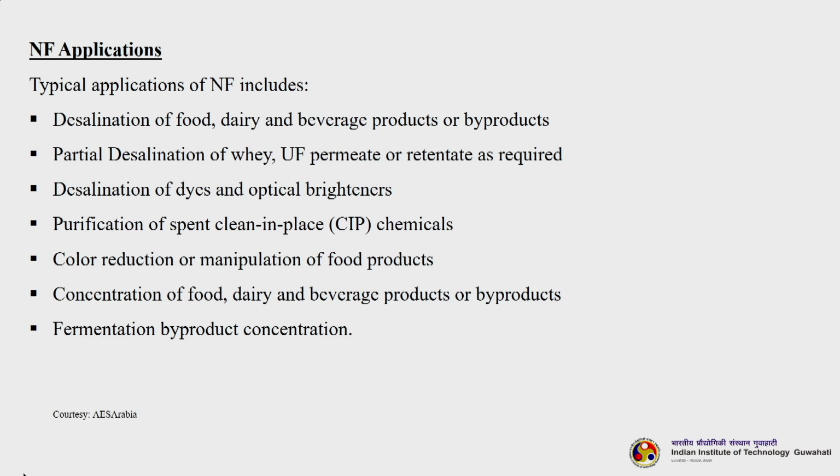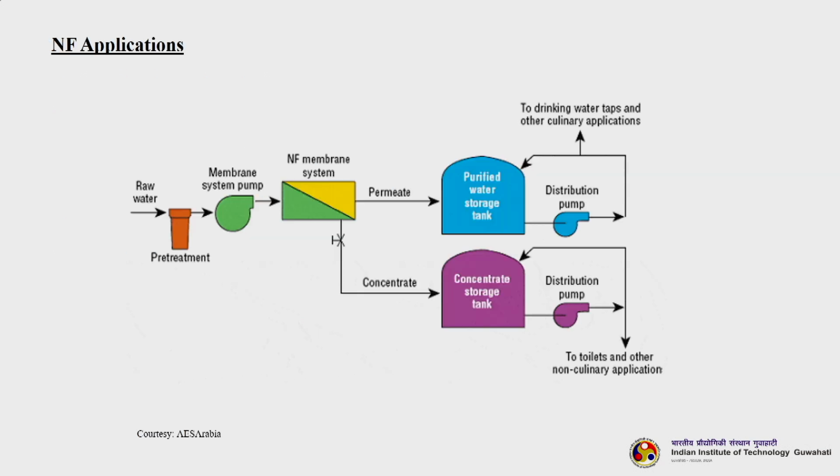So, NF applications include desalination of food, dairy, beverage products or byproducts, partial desalination of whey, UF permeate or retentate as required, desalination of dyes and optical brighteners, purification of spent clean-in-place chemicals, CIP chemicals, color reduction or manipulation of food products, concentration of food, dairy and beverage products or byproducts, fermentation byproduct concentration.